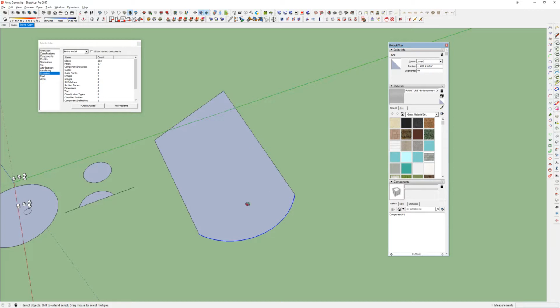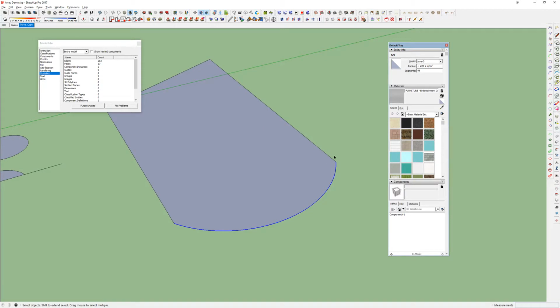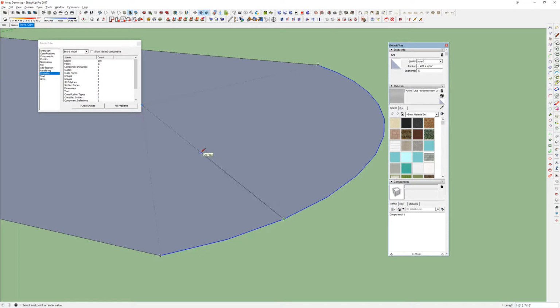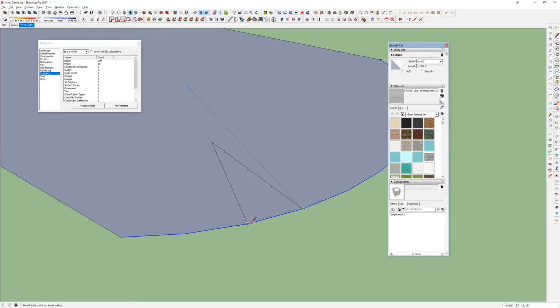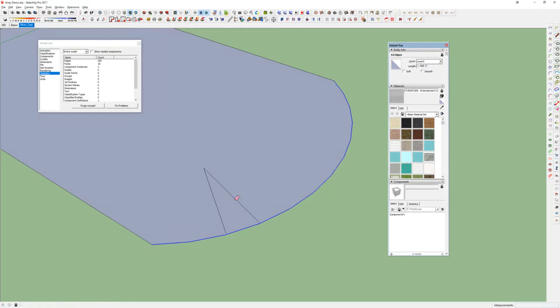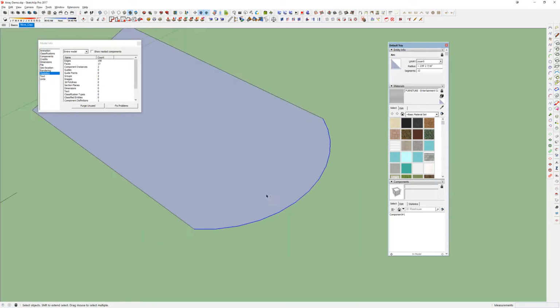It really doesn't matter. You just want a nice smooth arc, especially when you're doing site work, because if not, an arc comes in at 12, and you'll see if I put this at 12, and I've drawn a driveway or something, you can see how big this segment is. This segment actually measures 38 feet, which is pretty massive. That's bigger than a driveway, which is only 12 to 16. So that's why it's really important to have segment control in your arcs. Yes.